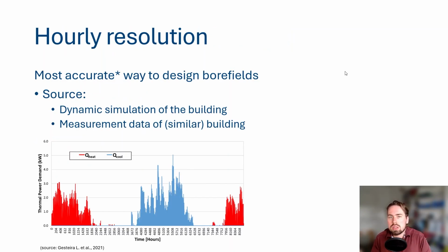So if you have an hourly resolution, you can calculate the bore field temperatures and required bore field size in the most accurate way possible. Now, there is an asterisk behind accurate, because it's not by definition the case that if you have data with an hourly resolution, with a high resolution, that it's also more accurate. For example, this hourly data can be obtained with a dynamic simulation or by measurement of perhaps similar buildings, but it's always important to take into account occupancy behavior and whether or not your data is representative for the building you're actually trying to simulate.